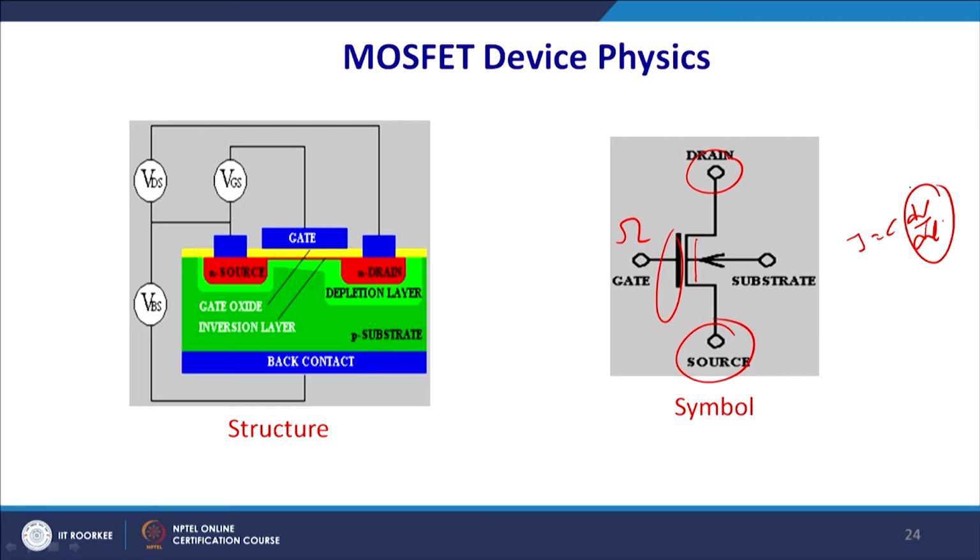So, ultimately the gate pulse frequency times C will be the amount of I, but since the value of C is quite low, the current also will be quite low. So, you are allowed to go to higher frequencies.